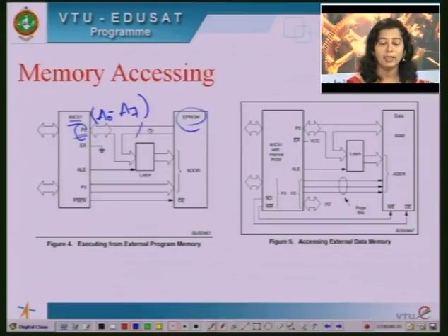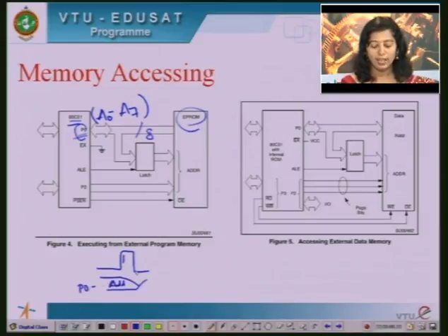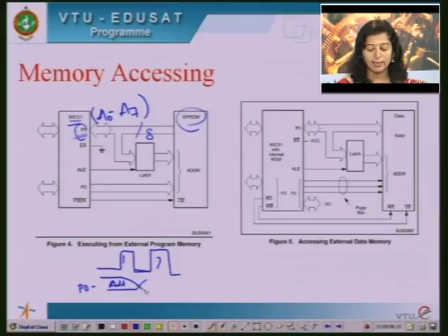So this is an 8-bit bus. So the same 8 bits will be carrying data in the next clock cycle. Maybe during the first clock cycle these 8 bits should carry the address. So P0 should have address during the first clock cycle, and during the second clock cycle the same value should have data. So the same 8 bits are going to carry data during the second clock cycle.